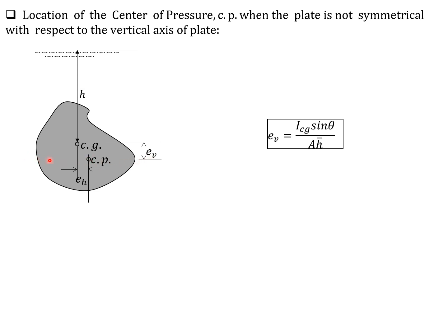And remember that if the strip is horizontal, the pressure is the same on this horizontal surface, because remember the principle that the pressure is the same at all points on the same horizontal plane in a homogeneous fluid at rest, or the distance of the horizontal strip from the liquid surface is the same. So the pressure is constant.